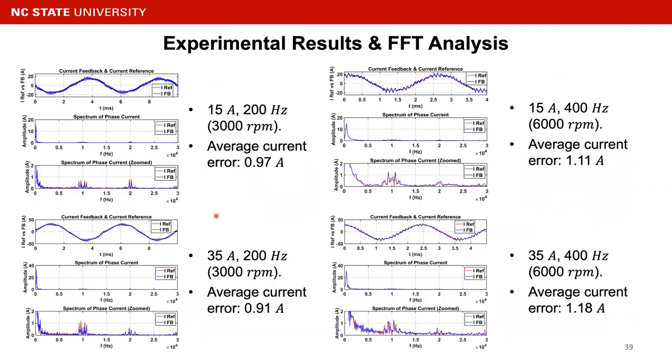And here's the experimental result and the FFT analysis. So we have 4 set points for our multi-emulator, with 2 current set points and 2 fundamental frequency set points. On the top subplot, we display the current feedback and the current reference. And then on the bottom 2 plots, we run an FFT analysis of the waveform.